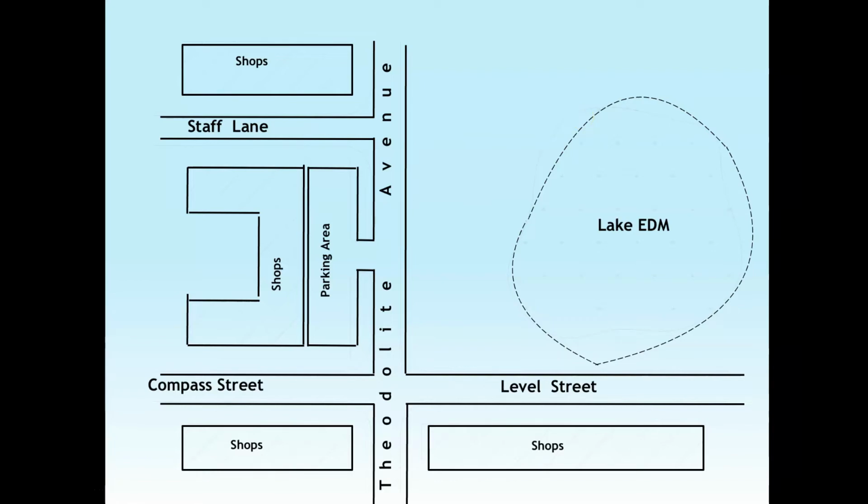So before you could start measuring all the shops and the streets and the parking area, the position of the lake, you have to provide the control. So you will have to go around the area, you establish points like so, the red ones. Okay, the red circles represent points that you have put in the ground, and you think that will be your reference point.